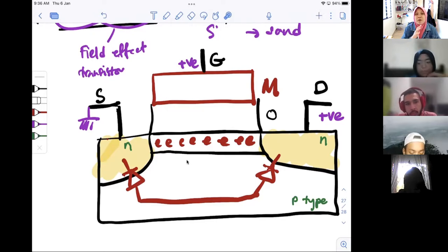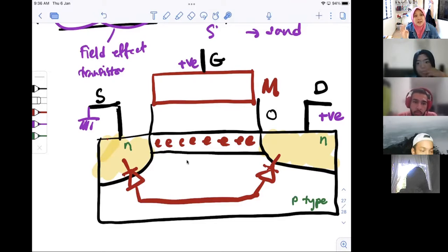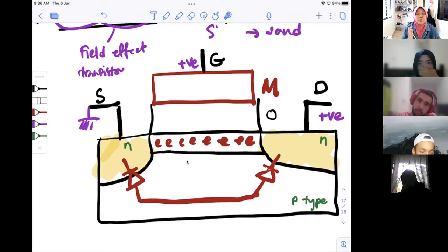When we talk about how a BJT works, we say electrons flow from the emitter to the base, recombine, and then are collected at the collector. At the same time, holes also move, which normally we don't say, but the holes also diffuse in the opposite direction of the electrons. So for BJT, both are happening. Even in a PN junction, electrons and holes move. But in a MOSFET, because of its structure and physics, only one type of carrier contributes.